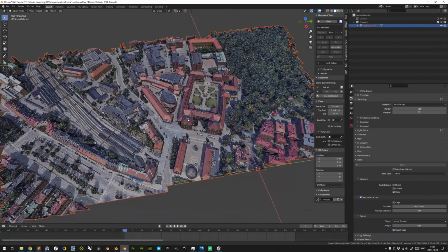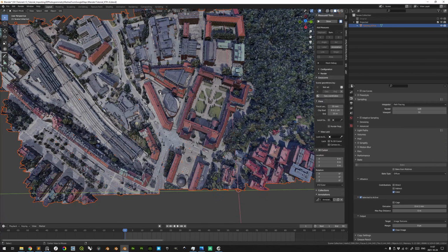One thing we could do is to simply pick a portion. Let's say we would pick out this portion of the mesh. We would delete everything outside of this, and then we would re-export this portion only to MeshLab, unwrap it the same way, and import it and bake it. Thus, each individual face would occupy a larger portion of the UV 0 to 1 space. That could be a viable solution.